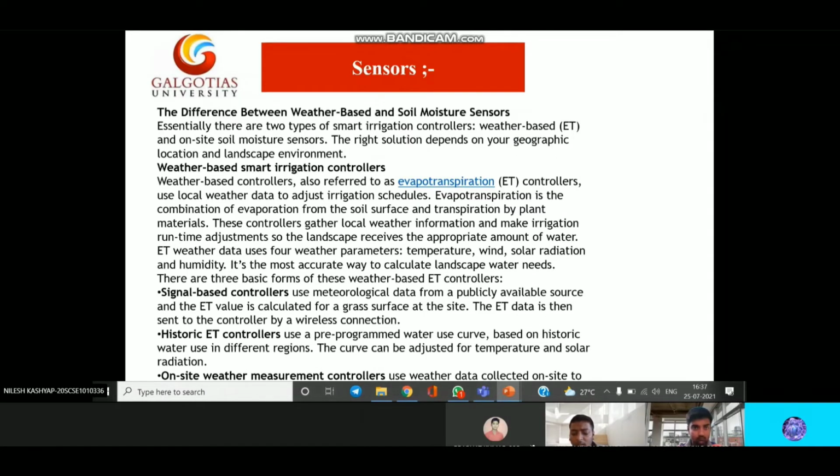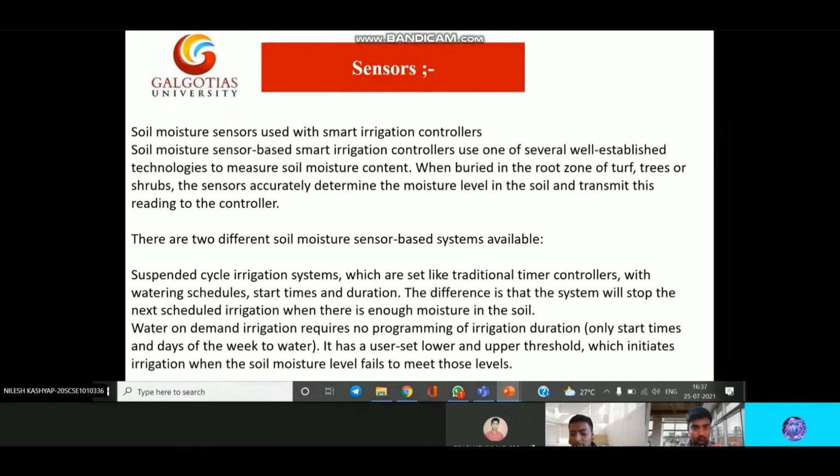The soil humidity sensor uses capacitance to measure the dielectric permittivity of the surrounding medium. In soil, dielectric permittivity is a function of the water content. The sensor creates a voltage proportional to the dielectric permittivity and therefore the water content of the soil. The second one is the water level sensor. The sensor that we use in this project is Arduino compatible and works on the basis of resistance measurement.